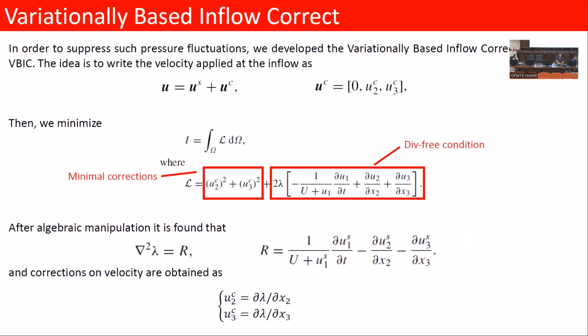Actually, I ensure the consistency of the velocity, because the synthetic turbulence generation methods don't know about boundaries. It's like an infinite domain, right? And you will have some velocity components which are maybe normal to a wall. And you need to suppress that velocity component. But of course, you cannot just put it to zero, because otherwise your field will get destroyed, basically. And this method is able to give you a smooth correction, which ensures that your boundary condition will be respected. The total velocity you apply will have the right boundary conditions.